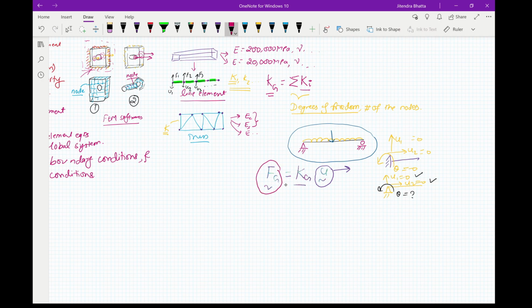Now these forces are the nodal forces that you'll obtain from your loading condition. For example, in this case, if this is your omega UDL, that's your length, then you'll get your nodal forces in this direction as omega L by 2 and omega L by 2.